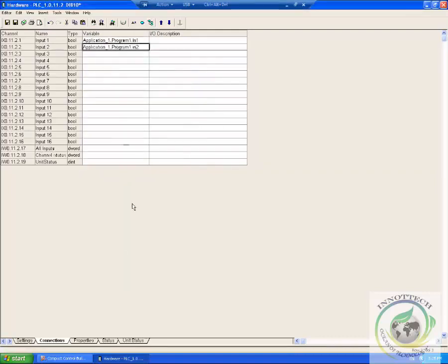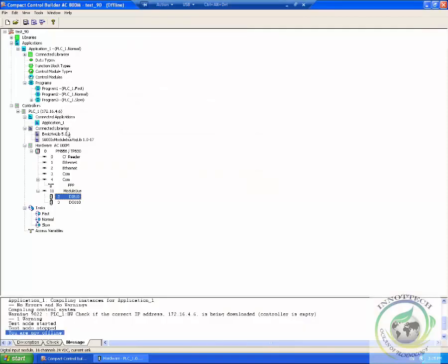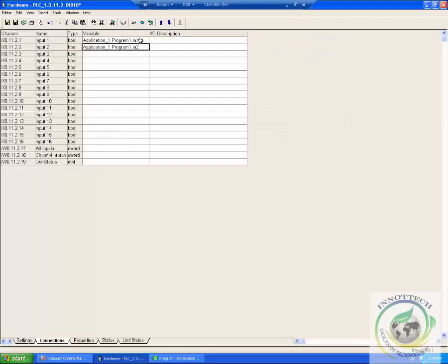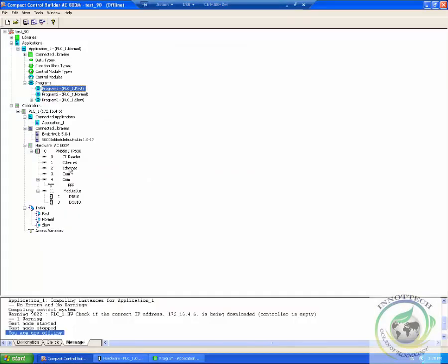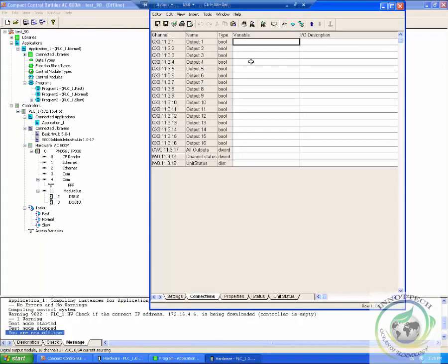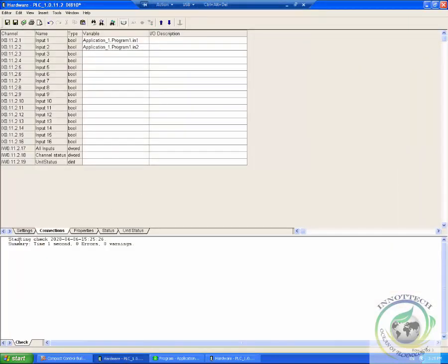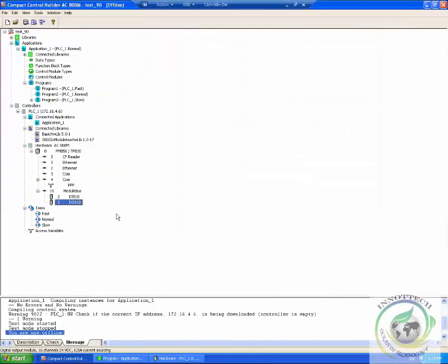So you created 2 inputs, and now you need to give them. These are the 2 inputs which are given to the digital inputs. So I'm considering this as the digital inputs. Okay. So I've given them over here. After giving it, we need to save it. So go to the hardware where you created digital inputs and click on errors. Check for the errors. After that, save and close it.